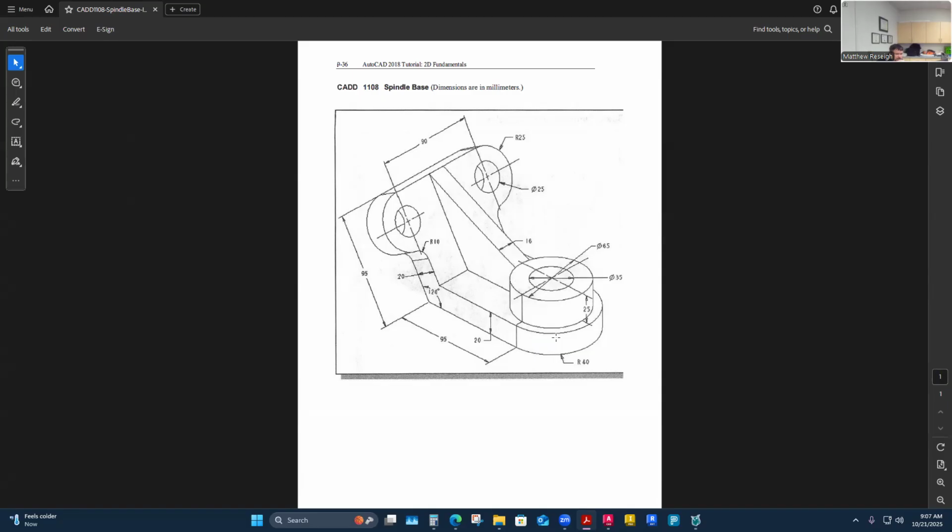And then it's going to be concentric to the big outer radius there. So I think I'm going to base everything off that 40 millimeter radius and put that in my front view, and then worry about some of these diameters, a 65 and a 35 diameter. So let me do that. And it's 25 millimeters above that surface that's 20. So 45 overall here, 20 plus 25.